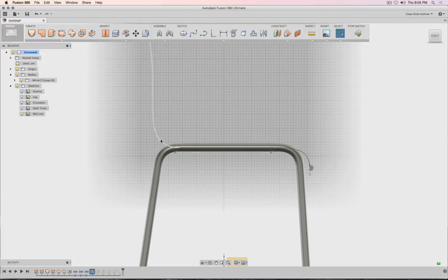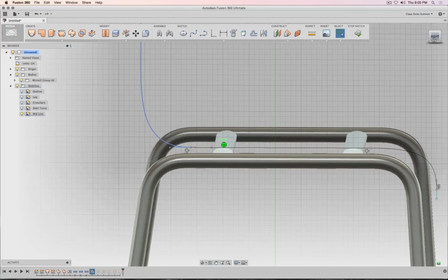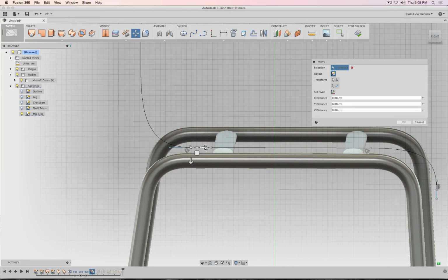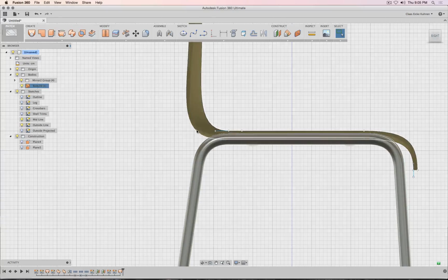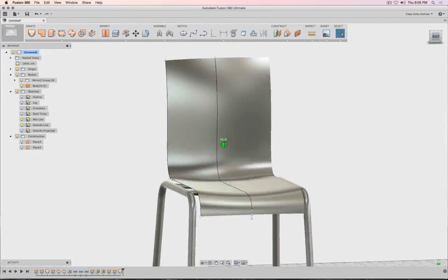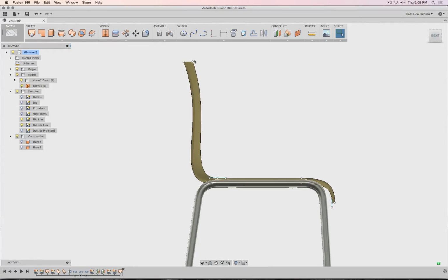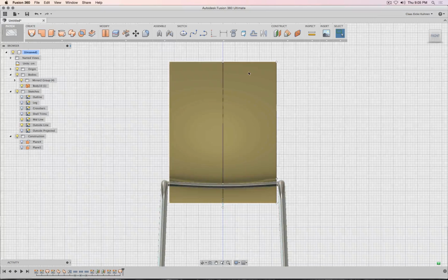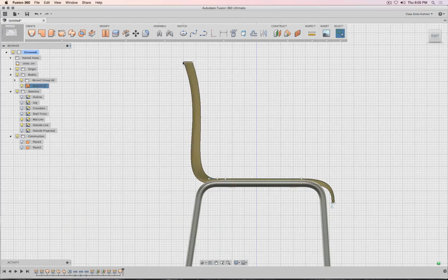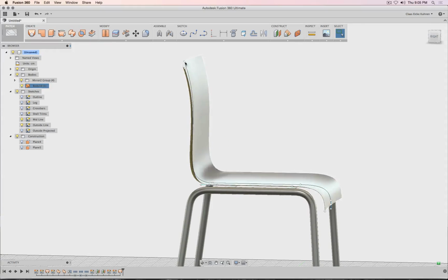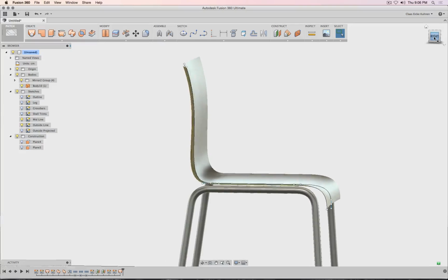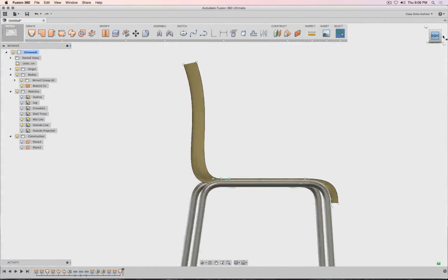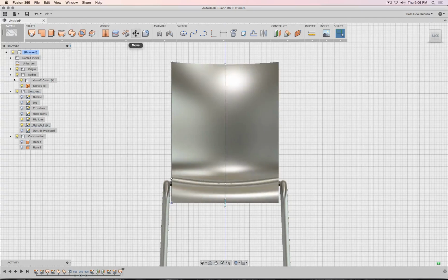Maybe actually here, let's go and edit that sketch. Maybe this point I would like to move back a little bit. Okay. See now how this bellies out a little bit more, and then to the top it gets flatter. Also, you can see from here this is horizontally straight. If maybe from this view I would like this to be arced, well, that's easy. Simply this point, we can click, select, move down maybe a notch, and there you see now it's arced. Maybe the same here. This one we move up. There.